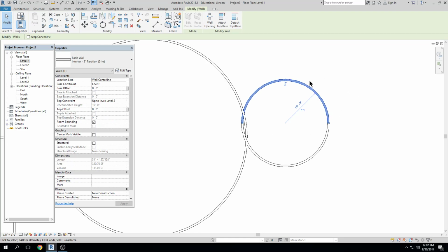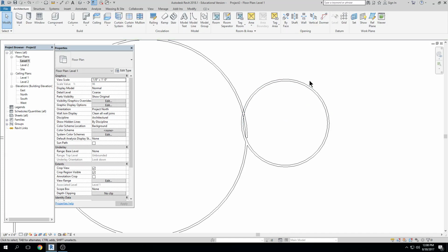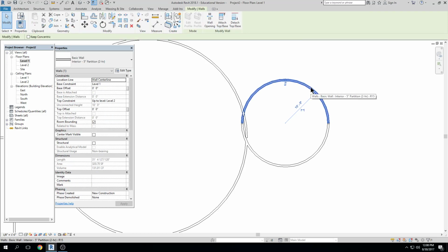Okay. If I would like to change that, I hit escape, I click on an item, and it reveals its properties. Another thing you're going to have to get used to in Revit is that properties and options don't always appear when nothing is selected, right? So I'll have somebody say, oh, I thought I wanted to change the radius of that circle, but I don't see where to do that, right? And I will always say you have to select an item to get the properties to show, right?